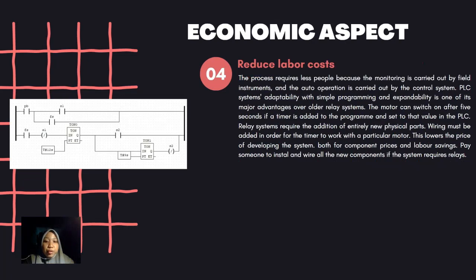Fourth, reduce the labor cost. PLC systems are adaptable and expandable, unlike the previous relay system. A PLC timer can be added to the program to turn on the motor after 5 seconds. With relays, the timers must be wired to a motor. A PLC can reduce the development cost, component cost and labor, saving the need to pay someone to install and wire new relay-based components.